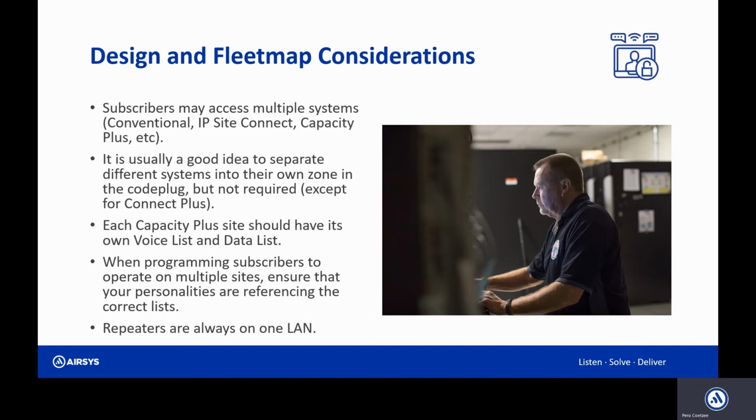Yes. And repeaters will always be on one LAN. So the networking for Capacity Plus is very simple. All the repeaters generally sit on the same switch. You don't need a router on the system unless you want to connect to the outside world and you want to remotely administer the system, or you've got a dispatch solution like Turbonet or so on. Otherwise, if it's a standalone system with no connection to the outside world, all of the repeaters can just sit on one LAN.